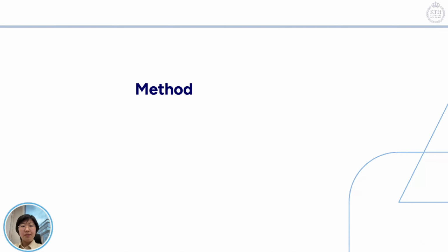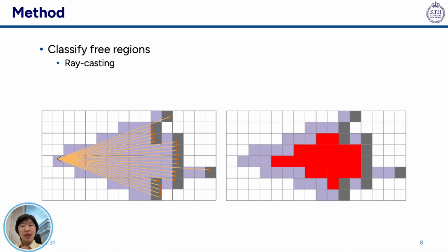So, the method. Actually, points are not only points, but also indicate more information about 3D space by using raycasting. For our method, raycasting is performed for each point from the sensor position. We propose to look at the direct neighbor of a voxel and the surrounding voxels to decide free space. Then the key insight is that if a region has been observed as empty at one time, like the red space here, a point observed inside this region at another time has to be dynamic.